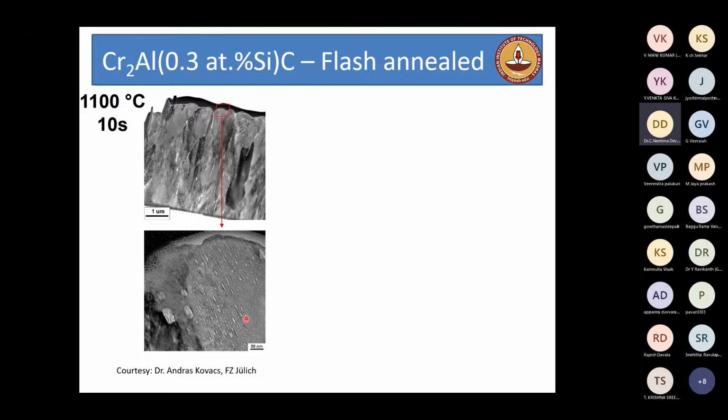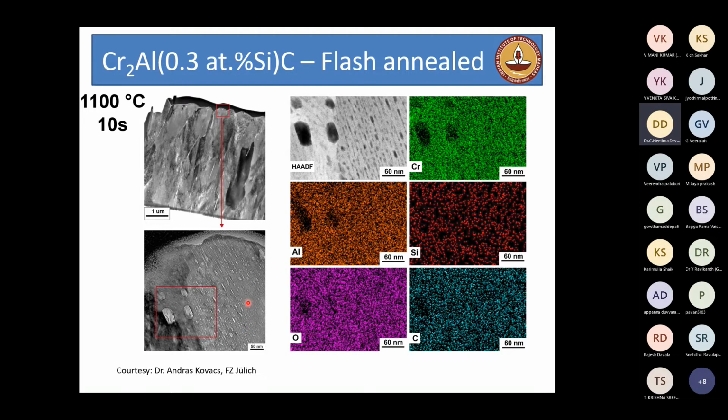Because in TEM, if you again do the chemical mapping, there is nothing you can identify to show whether these little precipitates along this region are enriched with something, because all elements are clearly depleted out of this region. This typically may indicate that there is no material present, or there is a void, or there is a halo.